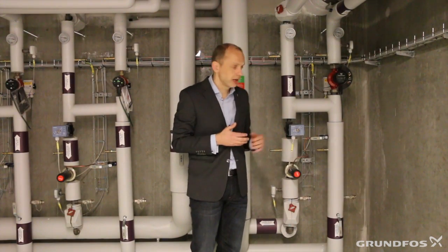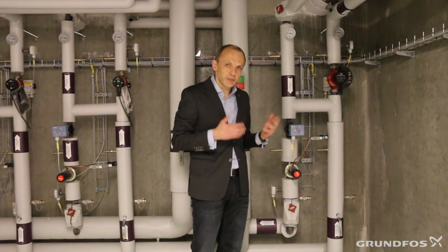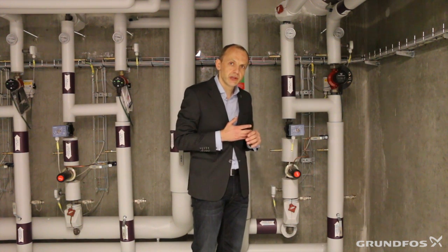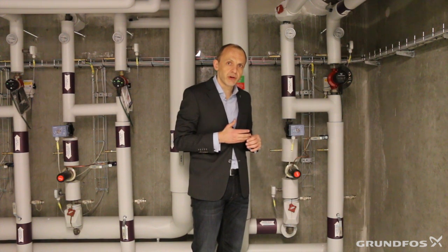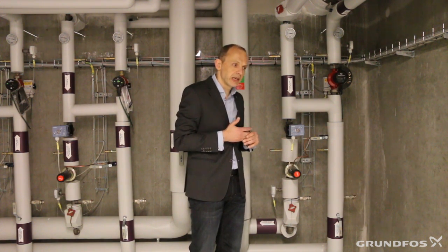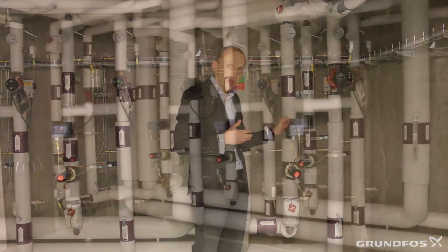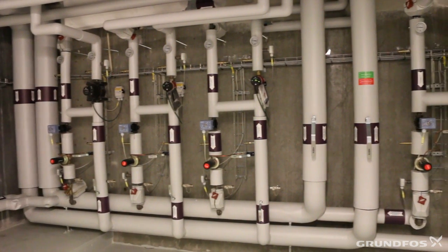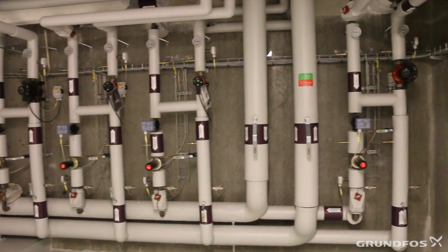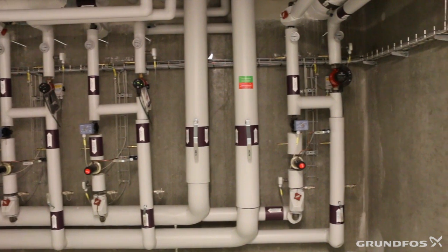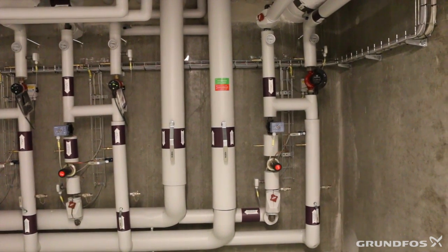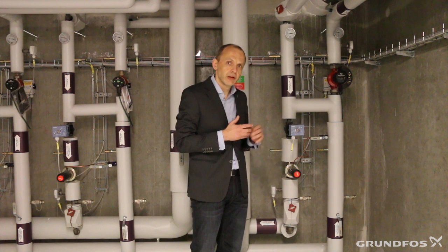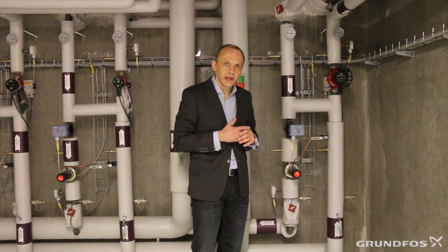Overflow on one zone, like this one for example, is a problem for a building, because that means that you have too high performance in the system, but it also has a consequence for other zones in the system. In this building, there's a number of zones with their own mixing loop. But if we have one mixing loop taking too big a share of the water, then the other mixing loops are getting too little water, which creates underheating in those areas that they are serving. That means that balancing of systems on zones is very, very important.